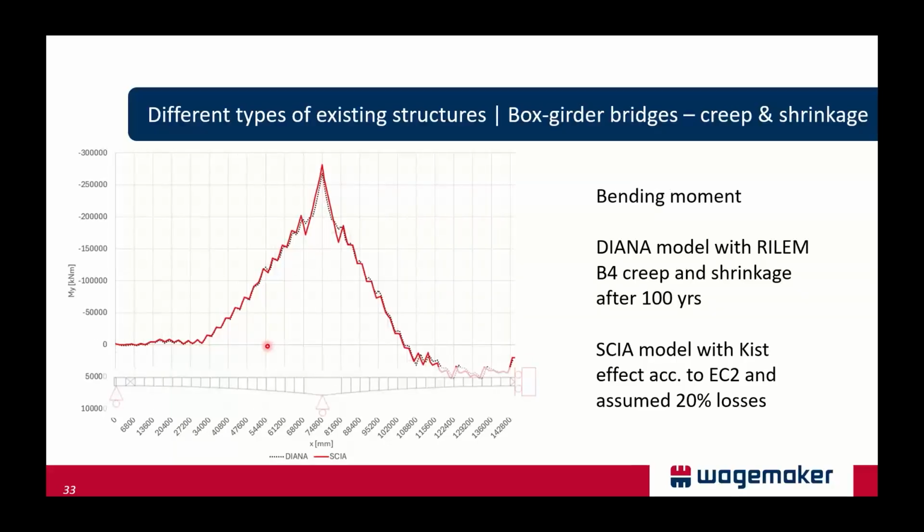And we did the same for bending moments. And we found also a very good agreement. So we were convinced that after doing this more advanced analysis, the simplified model and assumptions that were made there were in this case good enough, and it was not necessary to refine the time-dependent pre-stress losses that were put into that simpler model.